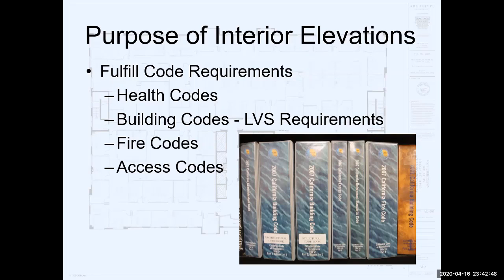If you're doing healthcare work for hospitals and so on, they're going to want to see every elevation that is relevant to your design. There are some basic codes that we deal with in terms of light, ventilation, and sanitation requirements, and those occur in the public restrooms that we provide in our designs.